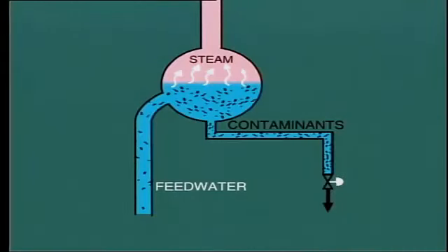But what is it that actually determines the pH of the water? Well, this all depends upon the makeup of the contaminants in the water, such as magnesium sulfate, calcium carbonate, silica, iron oxide, carbon dioxide, and others. Most of these contaminants are contained in the feed water in very small quantities, of course, but the concentration builds up in the boiler. It's usually necessary to add alkalinity to the boiler water in order to raise its pH and bring it within the prescribed range.